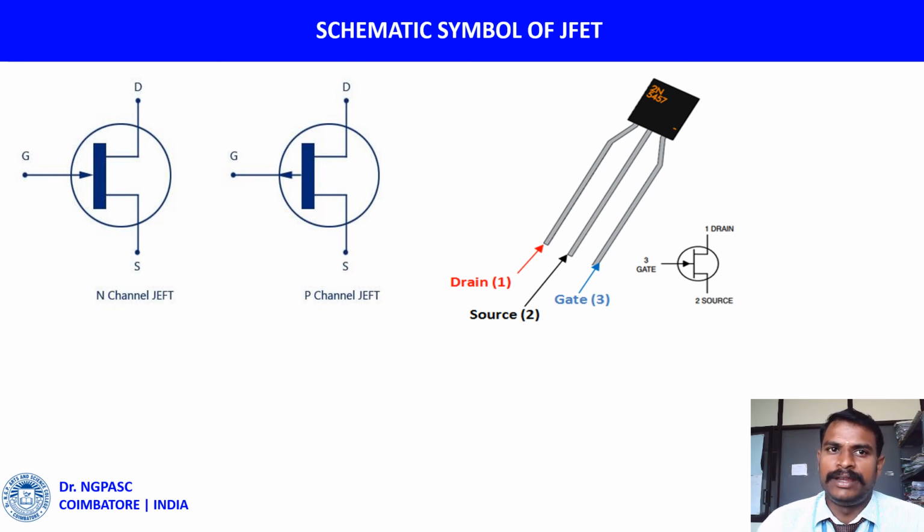The need for JFET: as modern electronic equipment became increasingly transistorized, it became apparent that there were many functions in which the bipolar transistor was unable to replace the vacuum tubes. Owing to their extremely high input impedance, JFET devices are more like vacuum tubes than the bipolar transistor, and hence are able to take over many vacuum tube functions. Thus, because of JFET, electronic equipment today is closer to being completely solid state.